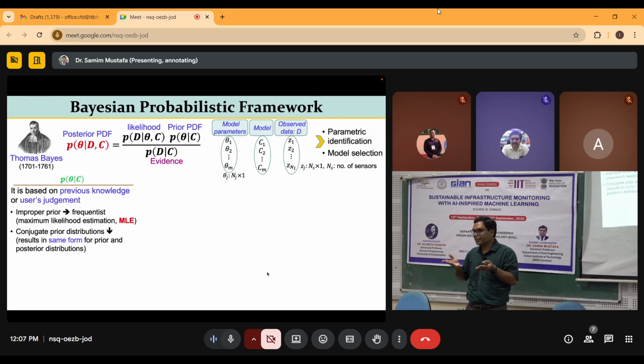Natural thing, right? So what do you want to do? You want a finite element model that is highly accurate. So you make an initial guess that is very close to the actual structure, not exact but very close. Then, based on the measurement, you update that model so that eventually the prediction from the model matches exactly with the actual response from the structure. So that is the goal.